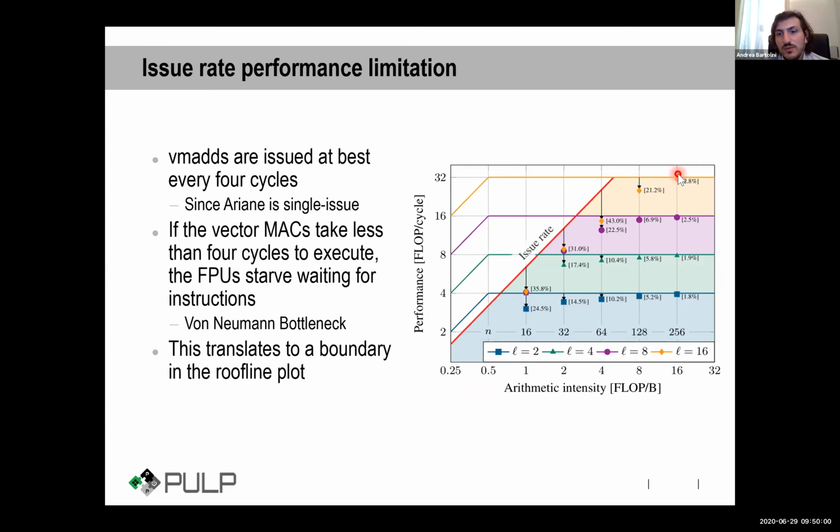With dots, we have a real measurement of the computation which can be achieved by running matrix multiplication kernels with an increasing n, moving to the right. And we can see, as is also expected for vector units, that by reducing the matrix size with respect to the peak performance capability of the vector processor, we have inefficiency due to the fact that the vectors become too small.